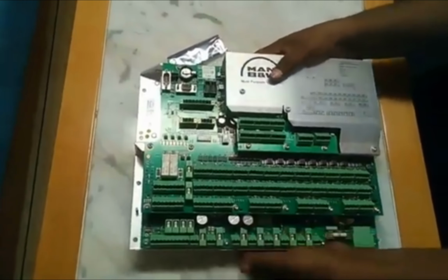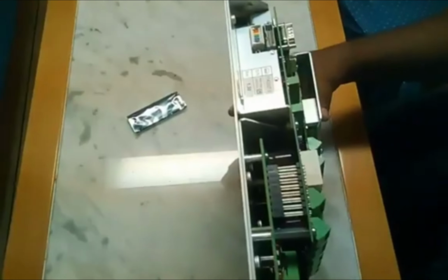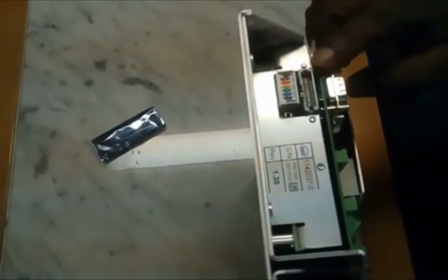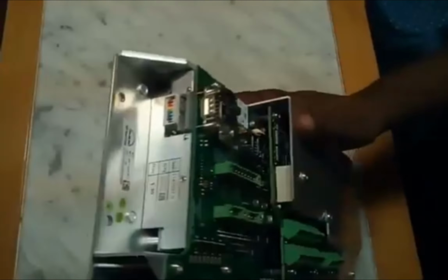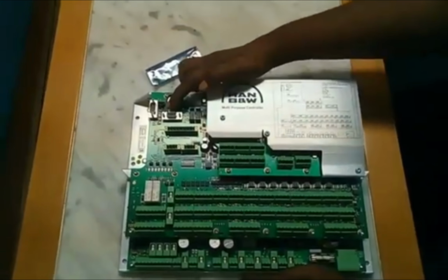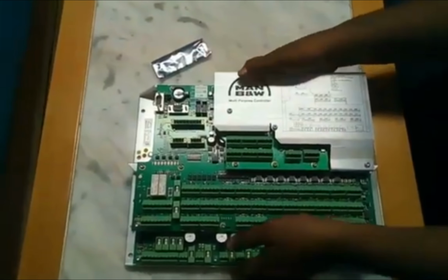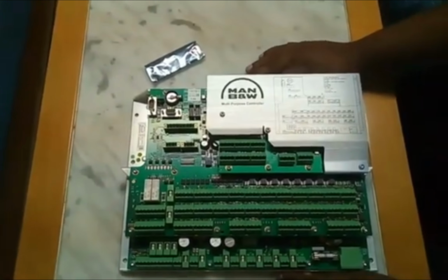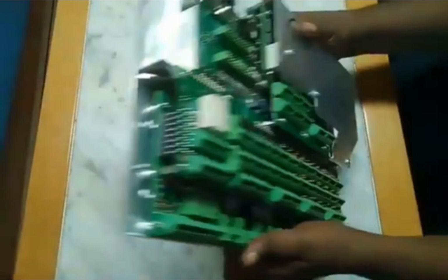One more thing is there, one more dip switch, I will show you now. This switch is for when you are changing the MPC. If you have trouble in the MPC, put number 4 switch, the yellow one, off, then connect all the connectors and channel connections, and put the dongle here. The dongle is the ID of the unit that is fixed for each unit, it cannot be interchanged, and with that ID, this connection is made, then all the software gets automatically loaded in this VCU.